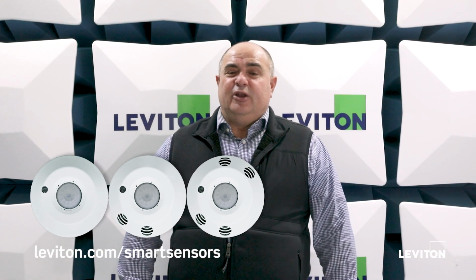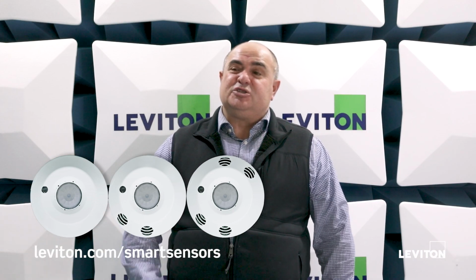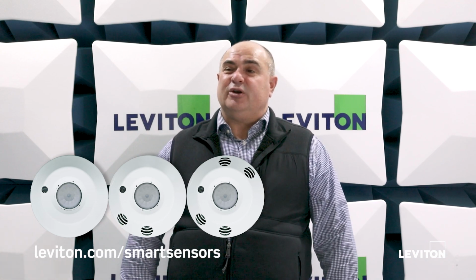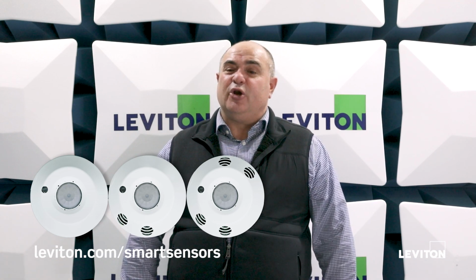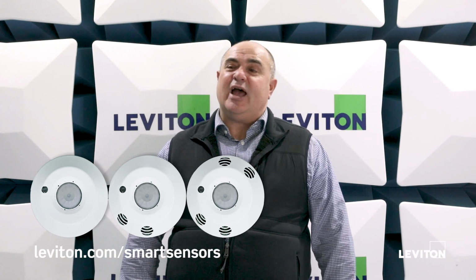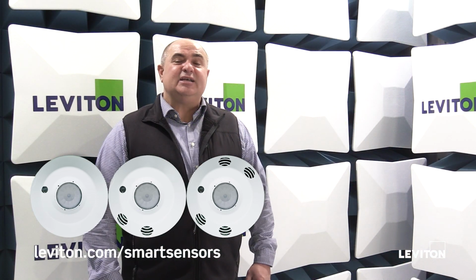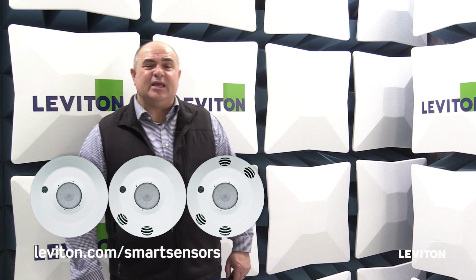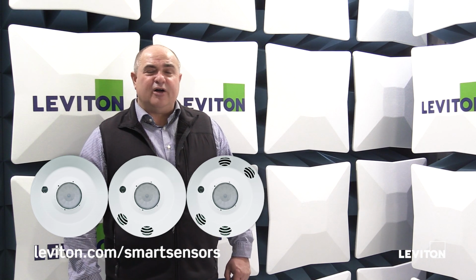If we compare that then to the smart ceiling sensor, the benefit of the smart room controller is that the smart room controller actually does now have the 0 to 10 volt dimming. It does have now code compliant daylight harvesting, as well as the partial on and partial off features.